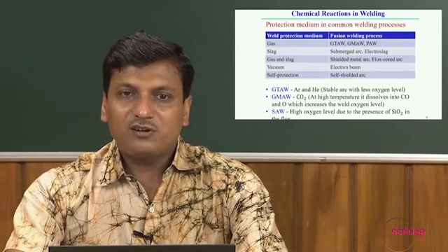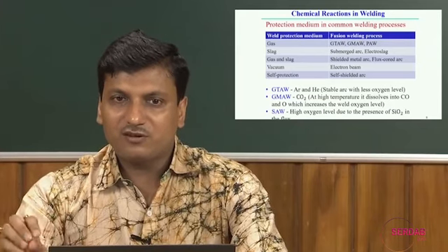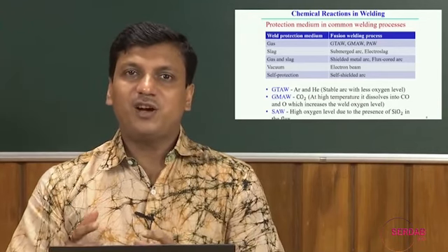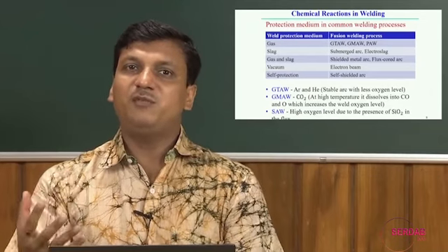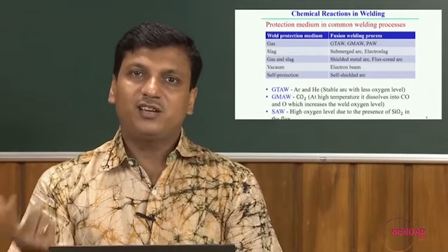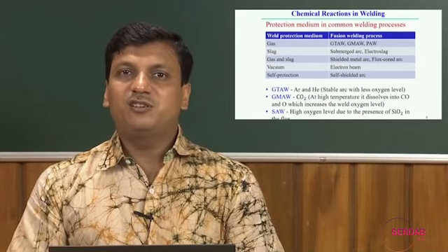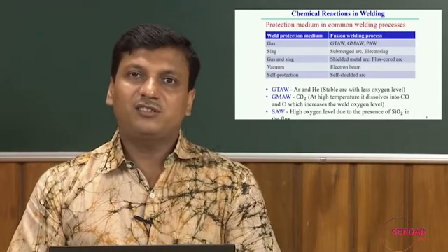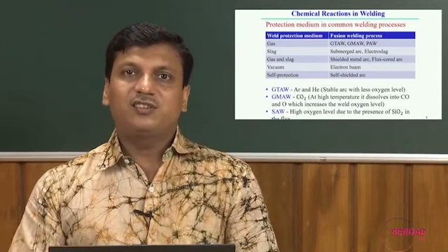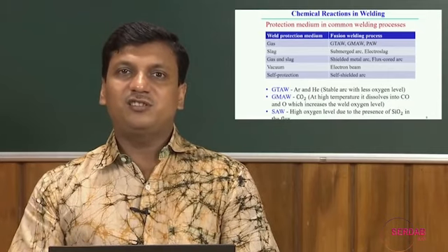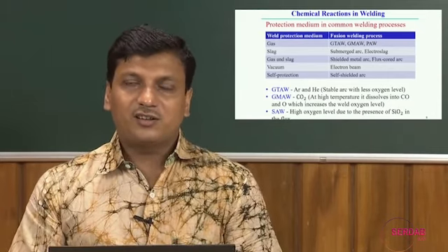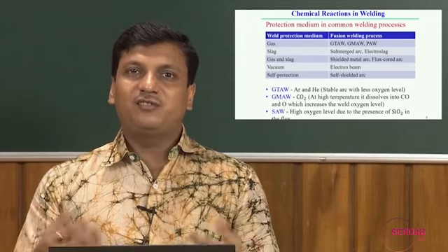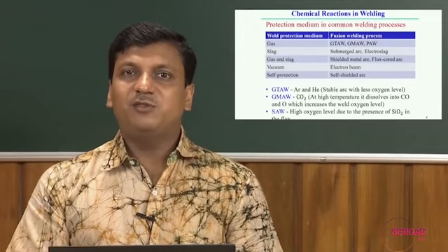Apart from all this slag, flux or shielding gas, it is also possible to combine different compositions of shielding gas. They may affect not only the shielding purpose, they can affect other aspects of the welding. Sometimes we use mixing with another type of shielding gas, mainly for the purpose of stabilizing the arc and concentrating the arc, and sometimes we intentionally use oxygen also, which can be used as a surface active element during the welding process.